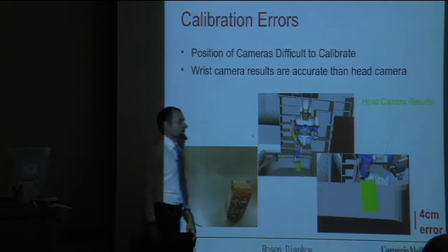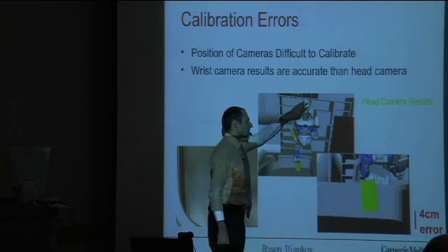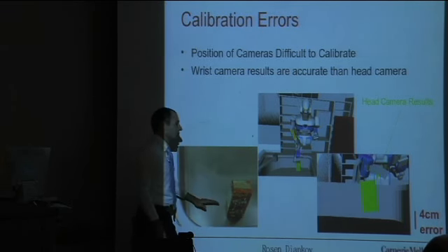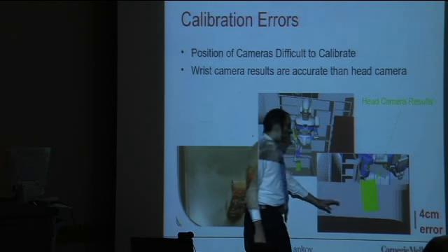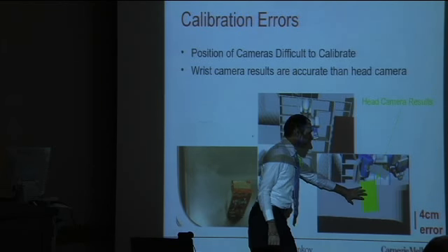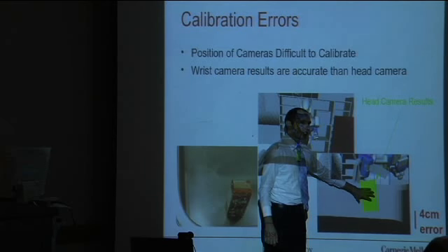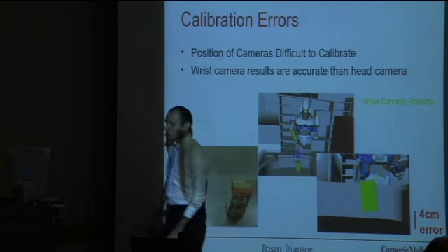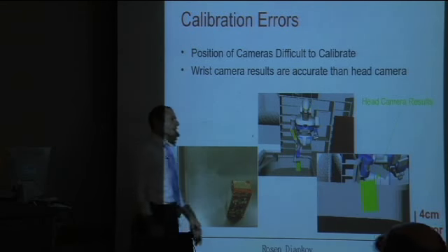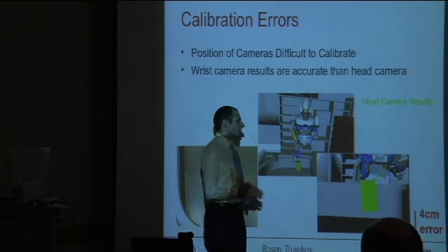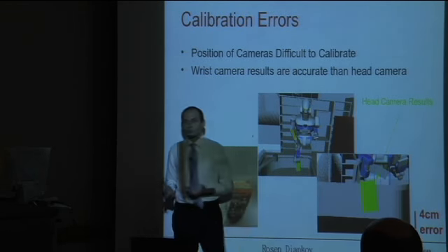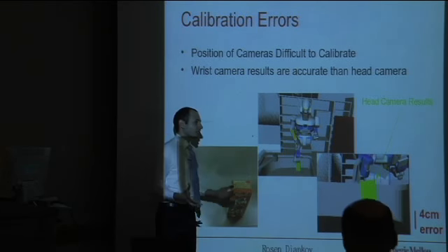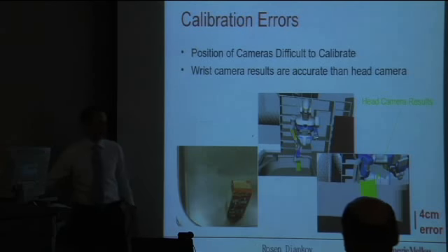There's also calibration errors. In this example, a humanoid here with its head cameras is observing this box, which is resting on a sink. However, the estimated object in the internal world representation is 4 centimeters away from the sink base. And even though it might not always be 4 centimeters, it's an error that the planning process has to compensate for, or otherwise it cannot guarantee 100% grasp execution.